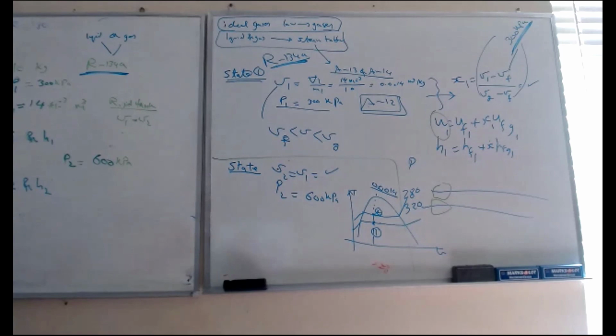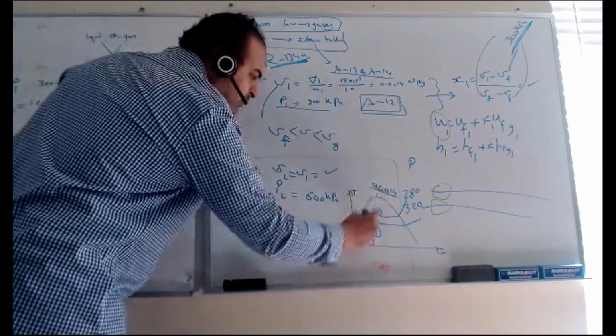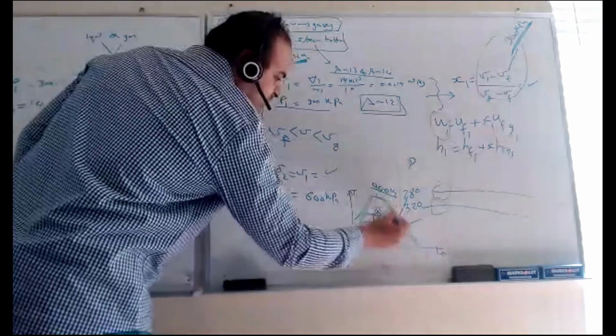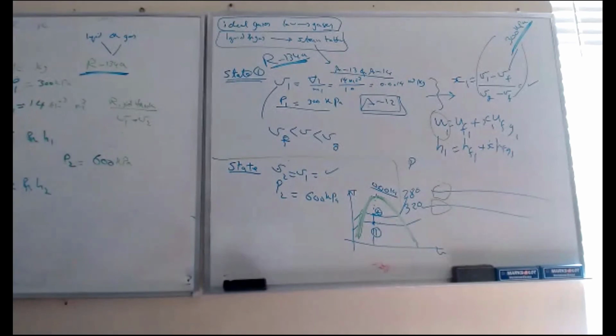The quality equation that you used on this problem, can that be used all the time, or only for saturated mixtures? Quality only applies in a mixture. If quality is 0, you have saturated liquid, the very left curve, x equals 0, only for this. If quality is 1, you have 100% vapor. So x only happens in between, from 0 to 1. It cannot be superheated or compressed liquid. It's only in the mixture between 0 and 1, so quality cannot be greater than 1.